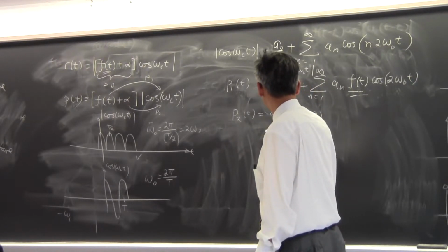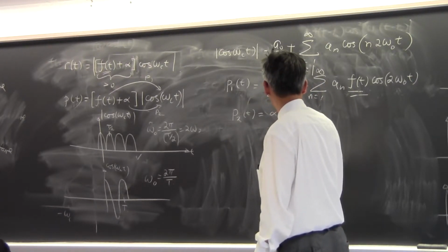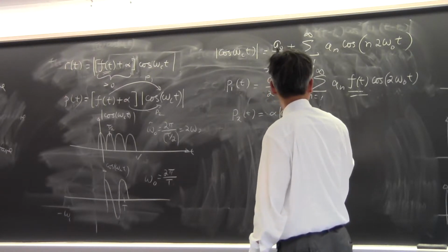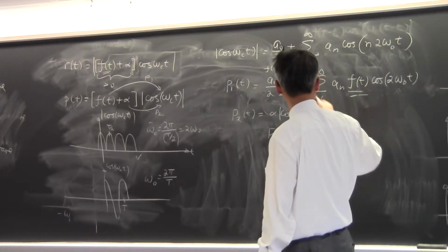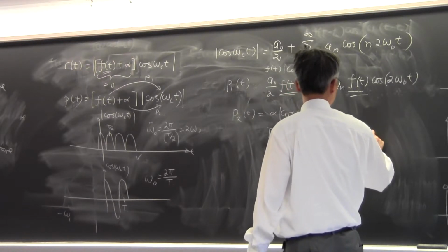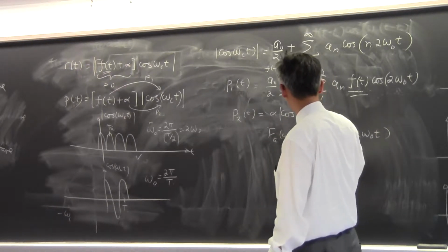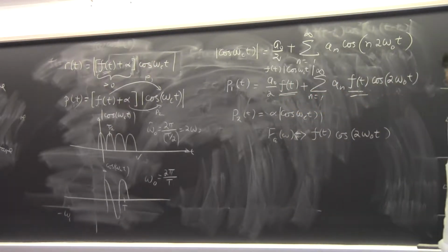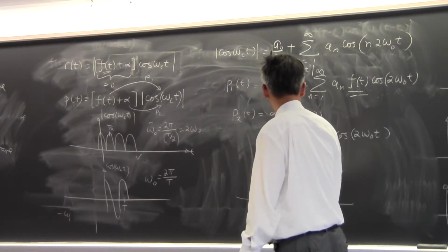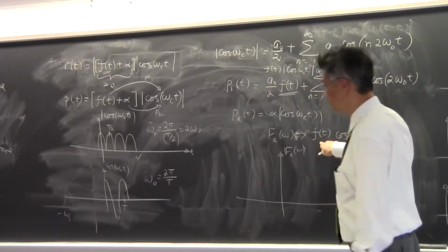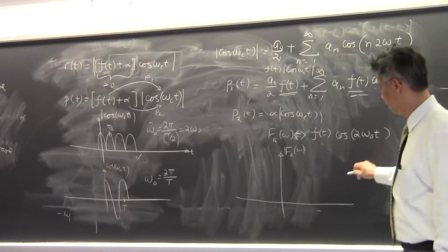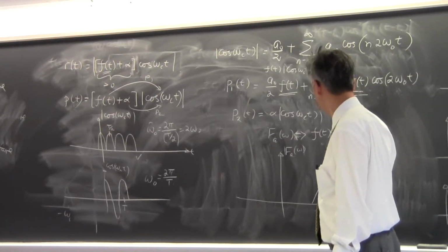So if I look at the spectrum, say F_a(omega), which is given by a Fourier transform of this f(t) cosine of n 2 omega naught t. Okay, if the Fourier transform of f(t) I call F_a, the spectrum of this would be just the spectrum of F_a times these two things. Okay, so it will be just right shifted and left shifted.